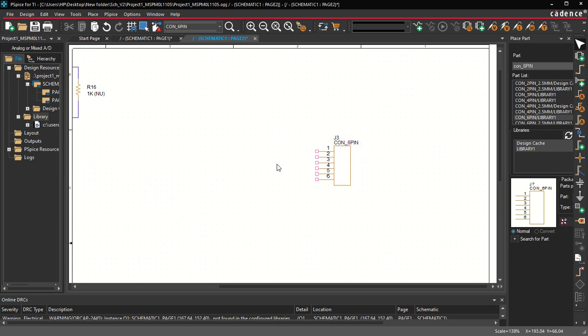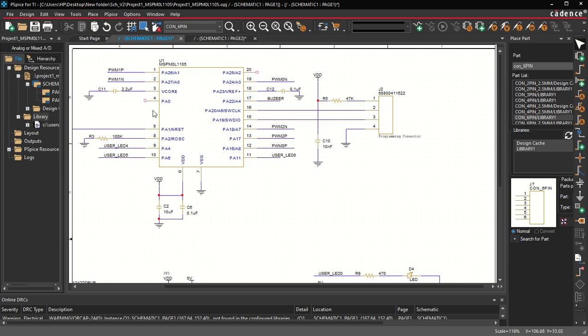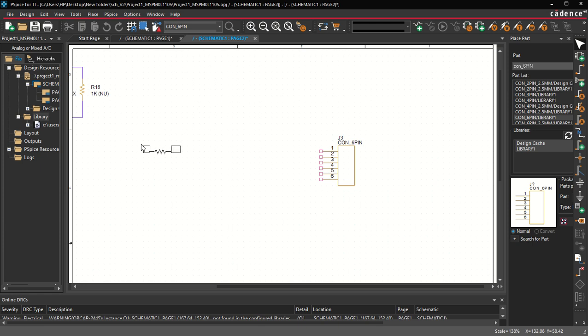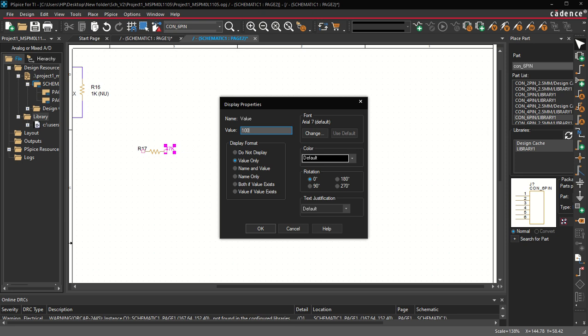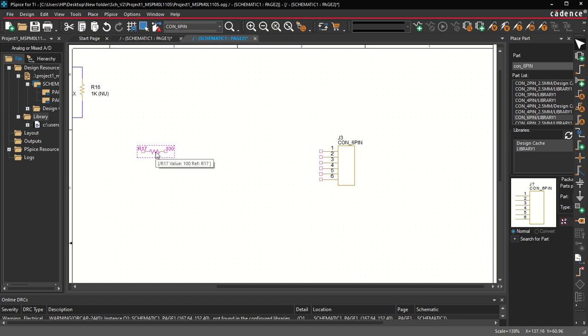Now we will put a resistor and capacitor also, like an RC circuit, so that we can have proper filtering before sending it to the connector. Okay, so we can have the RC circuit here, or otherwise in the motor driver circuit you can have the RC circuit there as well. So I will just show it to you here how to put it. That will be a nice idea. So what I will do is I will take one of the resistors from here and put it here, and let us say I am going to take this resistor as 100 ohm. Okay, and then make 6 resistors.